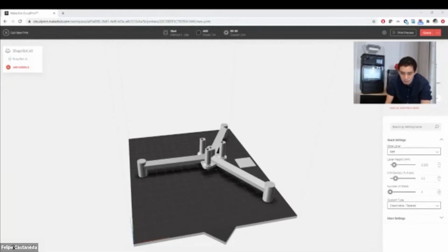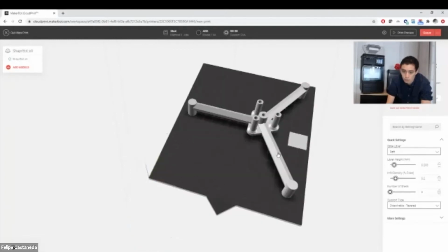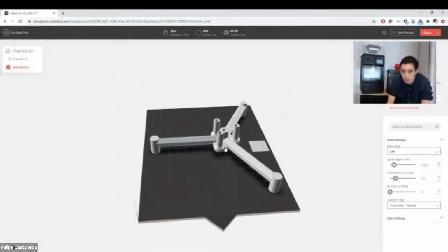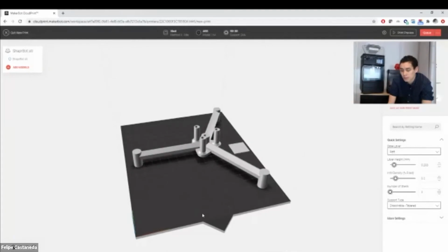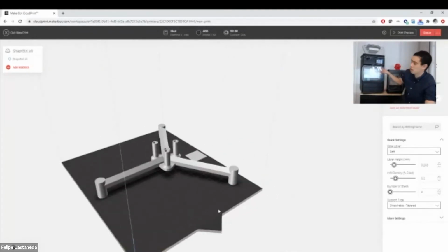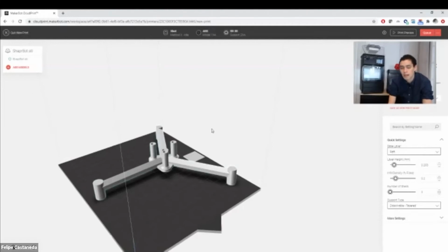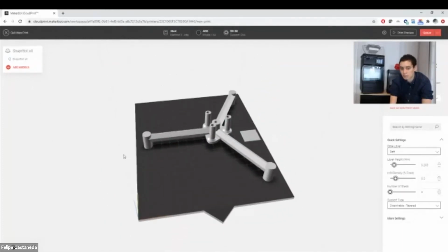And essentially, what I can do with Peter's model here, once it's done, is just import it to my print bed. In this case, I'm connecting to my local Method X here. It's loaded with ABS, as you can see here. Well, I'll just take you guys through the interface real quick. So this is a printer that I'm connected to locally here, loaded with ABS as the model material, SR30 as our soluble support material. And now here in my build plate, the representation of Peter's part, right?